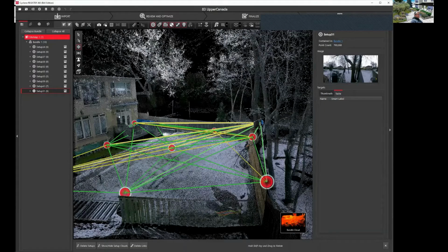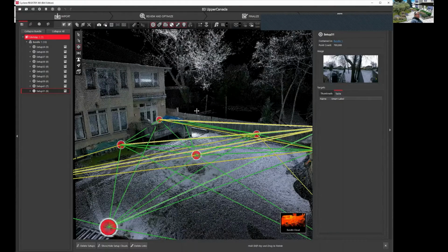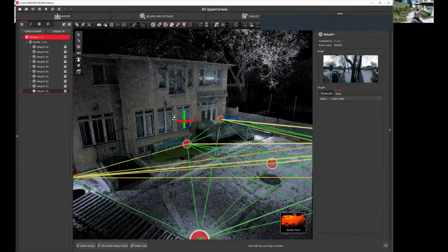And then I bring that back into the office and load it into the computer. It gives me a nice lovely point field. Then I can actually start modeling off that point field. I don't have to do any measurements. I don't have to take any photographs, because wherever that tripod is, I have highly accurate information, and I can't do anything better than that machine with a tape measure and a laser level or a zip line. The machine's accurate to, what was it, 1/4 of an inch or 6 millimeters at 10 meters, a minute to 2 minutes per scan. So it greatly improves your speed.